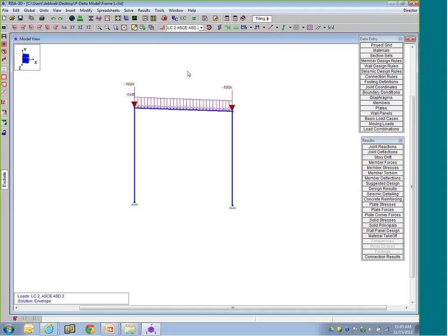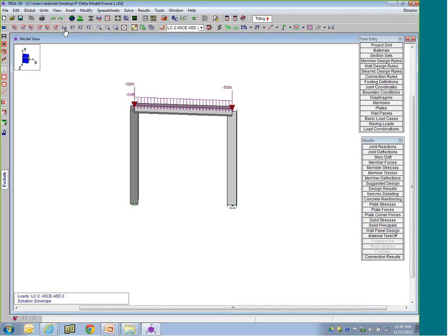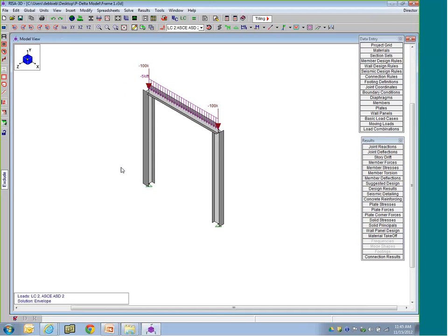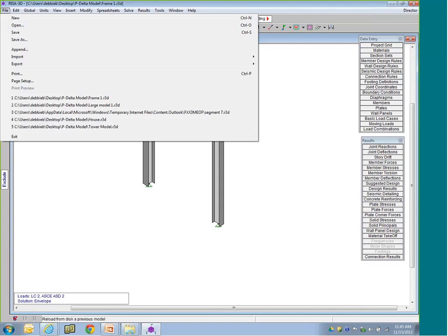This isn't a symmetric model, so you'll notice I did it a little bit unsymmetric, so you'll have one weak and one strong axis, so it is suggesting different columns for each side. So this one in particular here just shows us how we can upsize the members to help get past that P-Delta problem.